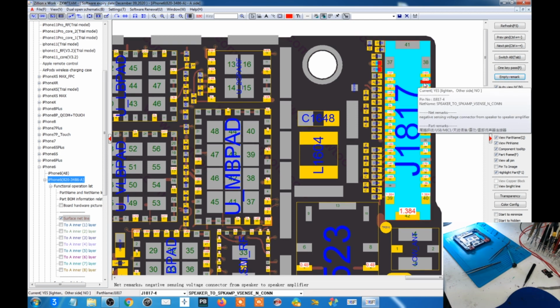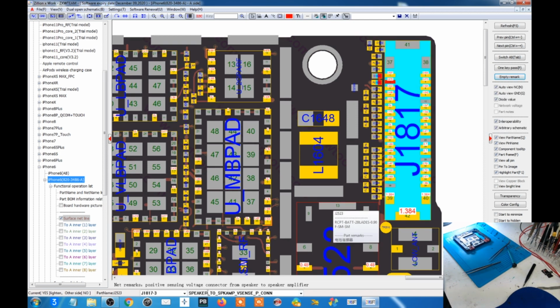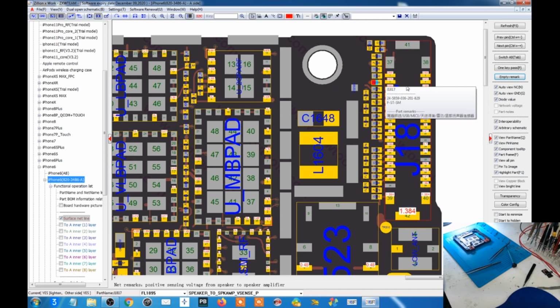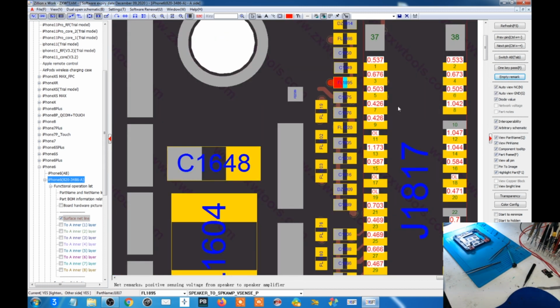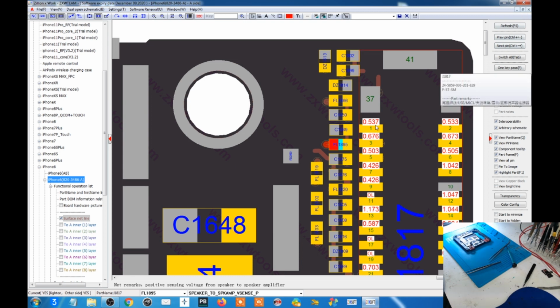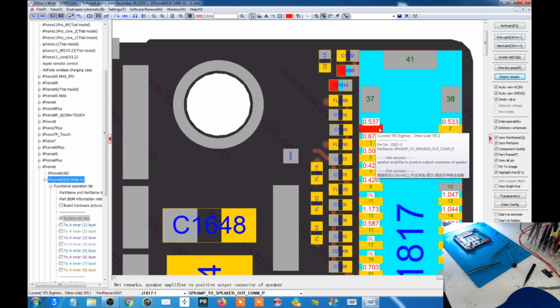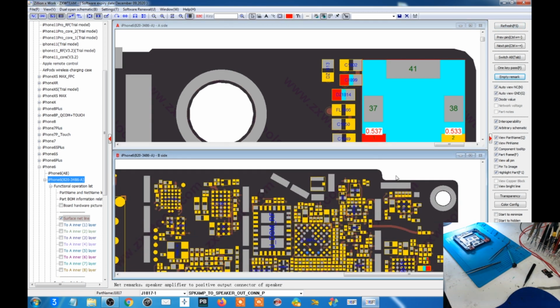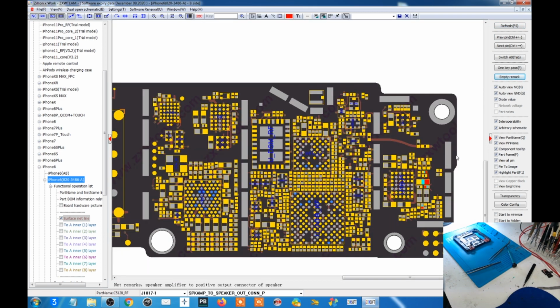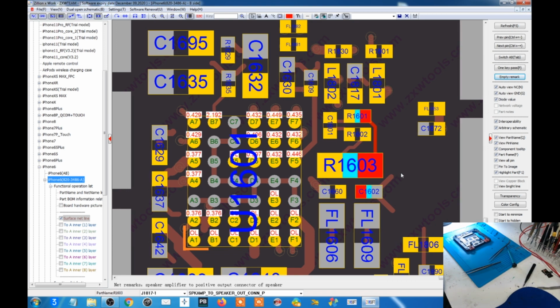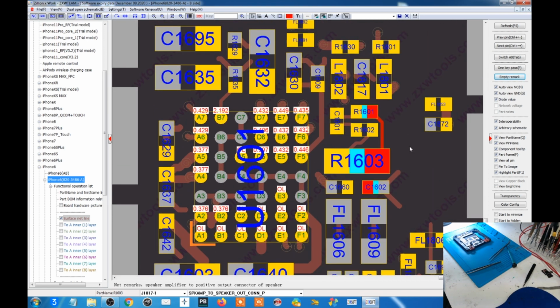And number 3 and number 4 are V sense. V stands for voltage, voltage measurement. It measures the voltage through the speaker or through the IC. Somewhere it has a fuse. So I checked the diode mode reading, and the diode mode reading was correct. So this supply goes through the diode, one capacitor, and goes over here through this resistance. There are two resistances.